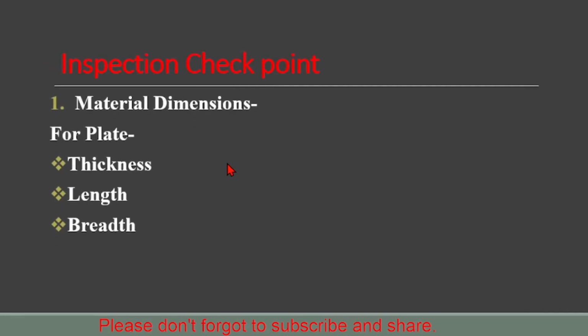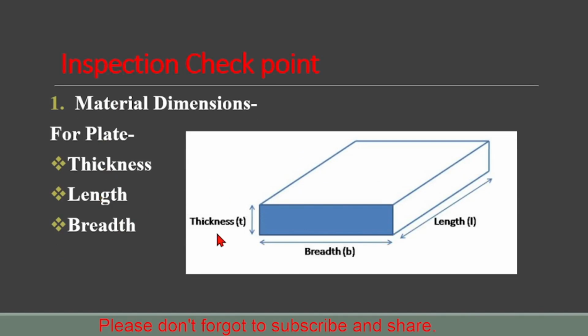So material dimension, after that we have to check the material dimension. For a plate we have to check thickness, length and breadth. When we receive the material inspection report or incoming invoice or challan, it is written what the thickness of this material is, what the length is and what the breadth is.